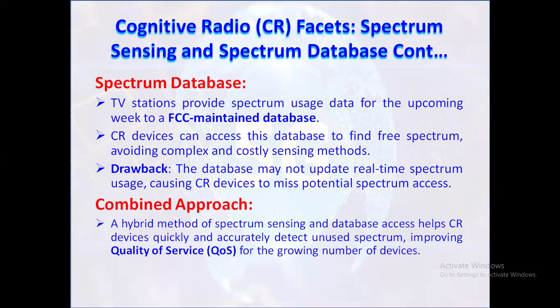However, there is a key limitation to this approach. The database is not updated in real time, which means CR devices may miss out on newly available spectrum if the database does not reflect the recent changes in spectrum usage. This can reduce the effectiveness of the spectrum use across the CR devices. This is the main drawback of the spectrum database.